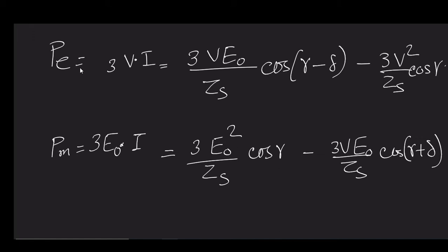when we get an extremely high value of regulation, like near about 80%, what happened is that we took a linear assumption and tried to anticipate that, had we allowed this much current to flow through our field winding and kept our terminals open, based on linear assumptions, what would be the amount of voltage we would have induced across our open circuit machine terminals, and that gave us that 80% or whatever.